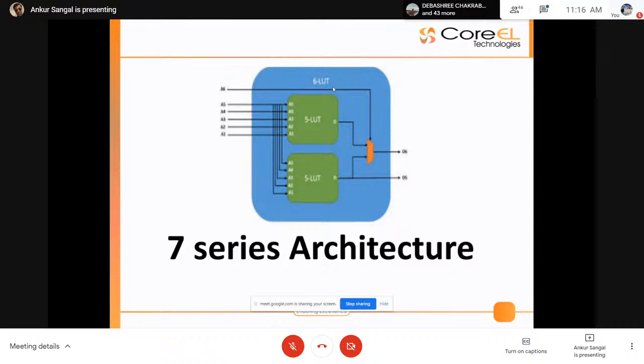I think all of you are aware that we have universal gates, NAND or NOR. Why do we call them universal gates? We can implement any Boolean expression with the help of NAND or NOR. Similarly, we can also implement any Boolean expression with the help of a multiplexer. Am I correct or not? Okay. So with the help of a multiplexer, you can implement any Boolean expression. Similarly, you can implement it with the help of a LUT, which you can directly recognize with a mux.